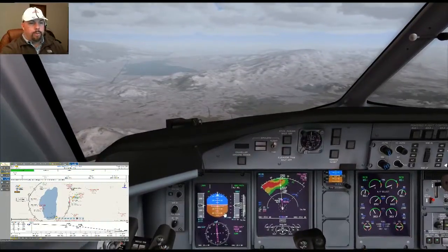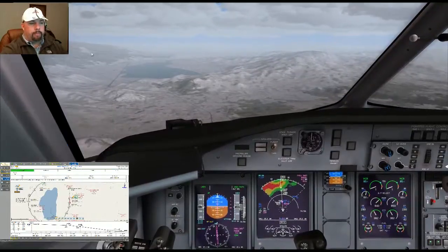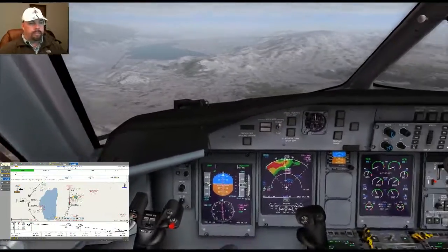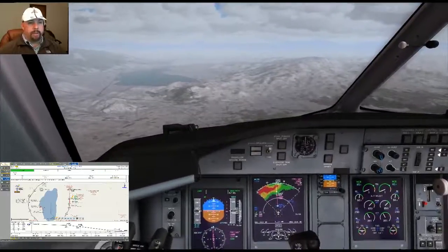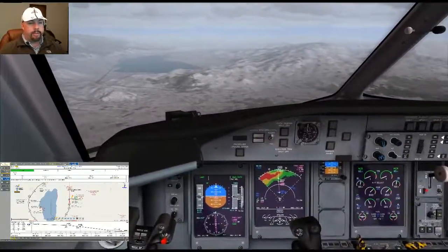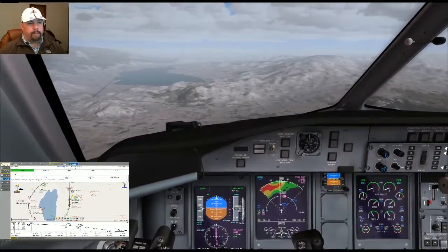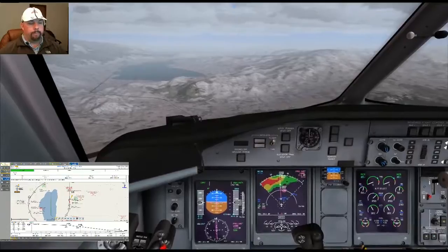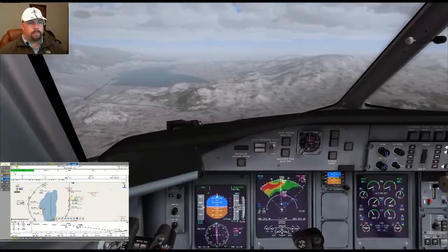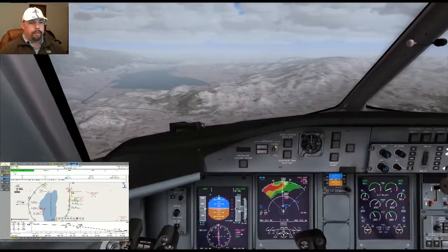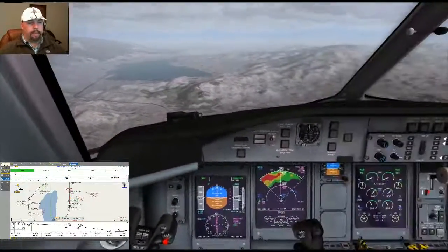So, in terms of the flight mode enunciator here, we're in LNAV and then VNAV. And again, typically on an RNAV, RNP approach, that would be the way you'd fly it. You'd fly it in LNAV, VNAV, whether you're in the NGX or the Dash 8 or the 777 or, of course it's not LNAV, VNAV in the MD-11, but it would be nav and profile. You can fly that all the way down to the missed approach point in LNAV, VNAV.